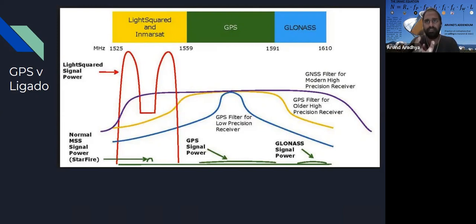Active devices have this characteristic called intermodulation. If you decide to sum two voltages, say in a diode, there's an exponential relationship, so the sum actually occurs in the exponent. If you remember a Taylor series expansion, that gives you square terms and cube terms and so on. Because these are trigonometric, these square and cube terms essentially result in an addition of frequencies and a subtraction of frequencies.